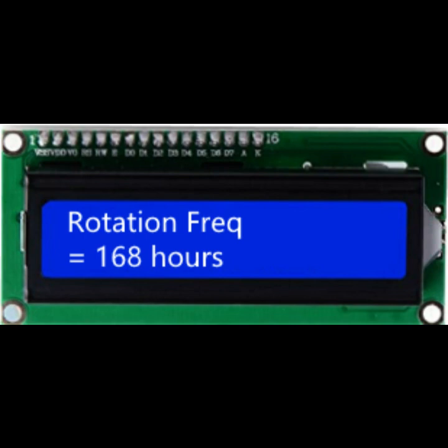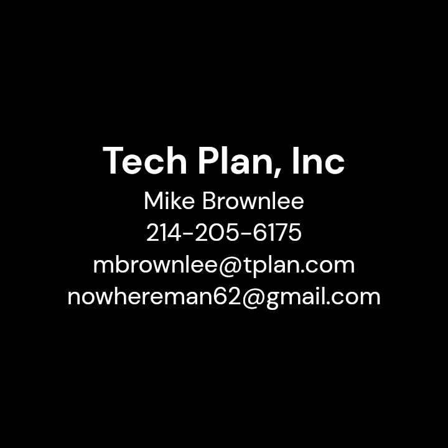Rotation frequency, this is where you can set the frequency in hours for the lead/lag rotation. For example, if you wanted the rotation to take place at the same time once a week, you would set this to 168 hours. The logic of lead lag rotation is, if the current date time is greater than the scheduled rotation date time, then a lead lag rotation will occur and schedule the next rotation for the current time plus the rotation frequency.